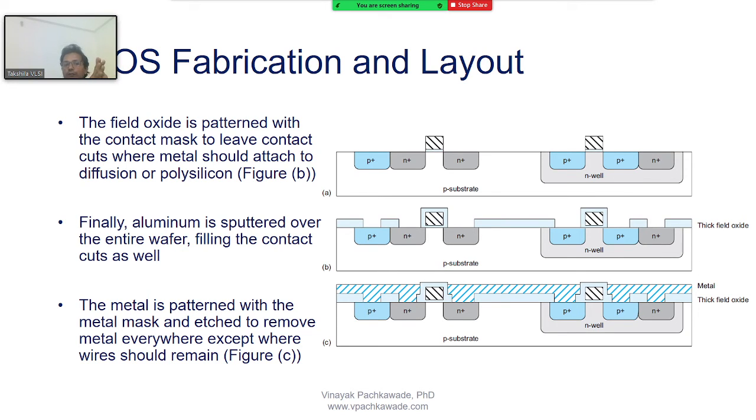Then I also explained to you, one by one, all the steps involved in the fabrication of this CMOS layout. When the layout is done, you do the verification. It means you pass some checks, you do DRC, LVS. Once your tool says thumbs up, you send the chip file to the foundry, and these fabrication steps that I just explained step by step will be performed at the manufacturing plant to fabricate your chip.